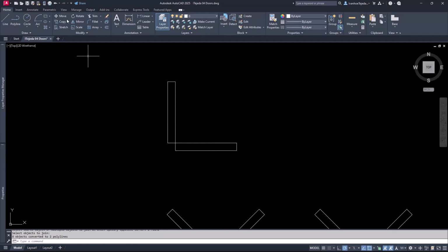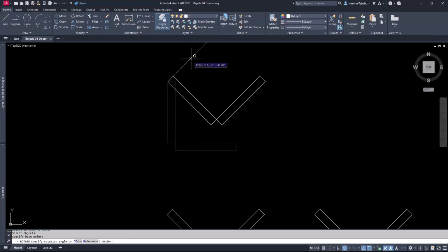And that's why I'm going to undo first. This is why I made sure that I joined these 2 line segments first. So I type J, enter. And then I took these 2 line segments and I typed J, enter, so that they're connected. Now I'll try again, select it, type J, enter, and it is now 1 closed polyline. And then finally, RO, enter, select my polyline, enter, rotate from this point to a 45-degree angle like that.